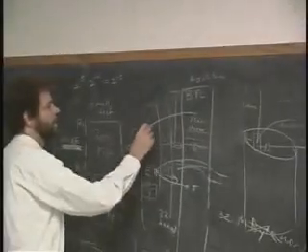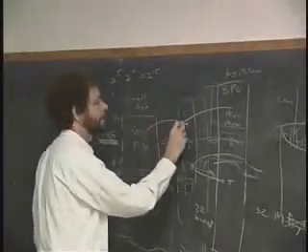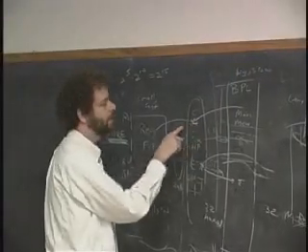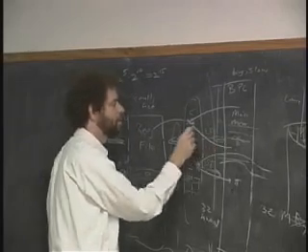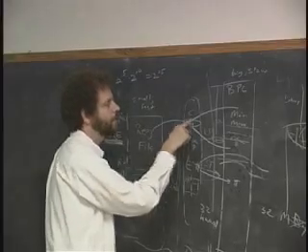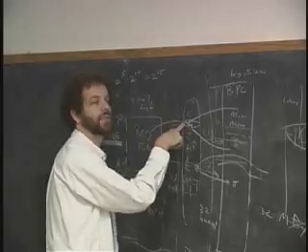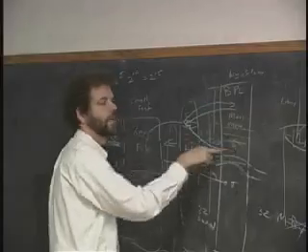So if I do a load from one location in the memory into the cache, the dirty bit is 0. If I then do a store and write that location in the cache, the dirty bit gets set to 1. If later on I read another location in the memory, which replaces this item that I have updated here, I need to write this back to here before I bring the new one in. And so I check, is the dirty bit 1? If the answer is yes, I go ahead and I write it back before I bring this in.